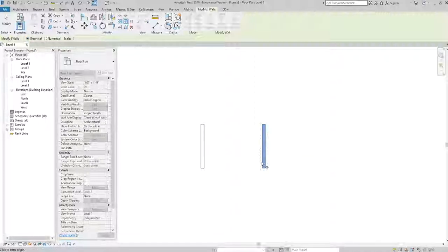The way that this command functions is it says, okay, first of all, you need to tell me how big this object is. And I know Revit inherently does know it's 9 feet long, but it wants you to specify maybe what portion of the object is being scaled. So it could be potentially less than that, right? But I'm going to say, well, I'm going to scale this whole object. So from the bottom point, click, to the top point, click. I've just specified how big that object is.